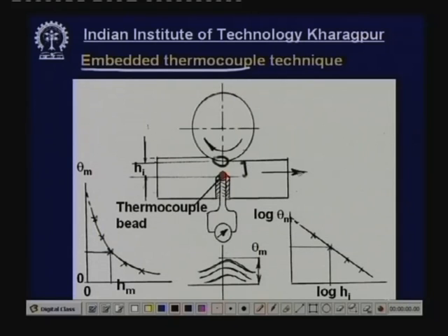Now, when you conduct the machining work, say with Vc and Vw, the job will travel in this direction, and this is the height Hi. Suppose this is at a particular Hi. This hole was somewhere here. Gradually it will move and come close to the grinding zone and then pass out. So, the temperature in this bit will gradually rise as it gets close to the cutting zone where heat is generated, and then it will gradually decrease.